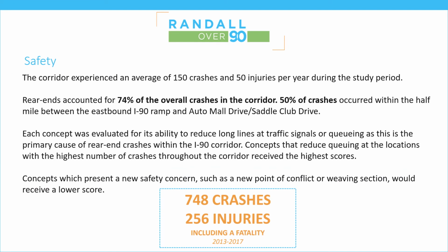Safety. For the safety category, each concept was evaluated for its ability to reduce the crash frequency in the corridor. An average of 150 crashes a year was reported to police in 5 years of data analyzed by the project team. Rear-end crashes accounted for 74% of the overall crashes in the corridor. Long lines at traffic signals, or queuing, were found to be the primary cause of rear-end crashes within the I-90 corridor.